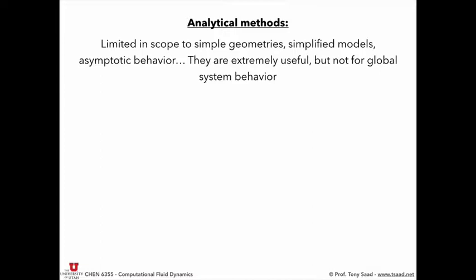And actually, Poiseuille was a medical professional. He wanted to study the blood flow profile in arteries. And so he approximated the artery as a cylinder with a fixed pressure gradient. So there's high pressure at one end, low pressure at another end, trying to mimic the action of the heart, and how the blood flows. And he derived an analytical solution for the flow inside a pipe.